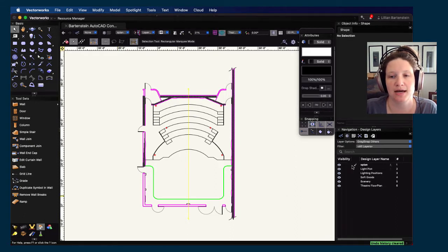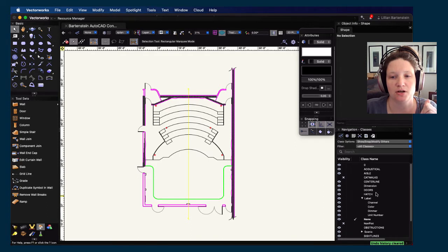So that is now XPlan on its own layer, and it's also brought in a whole bunch of different classes. You'll see them because they're all caps. Those all caps classes are your Vectorworks conversion from AutoCAD classes, okay? You'll also see a lot of things are different neon colors. That's common with CAD drafting because their classes typically determine line weight and they use bright colors to differentiate. But in any case, there's our plan.